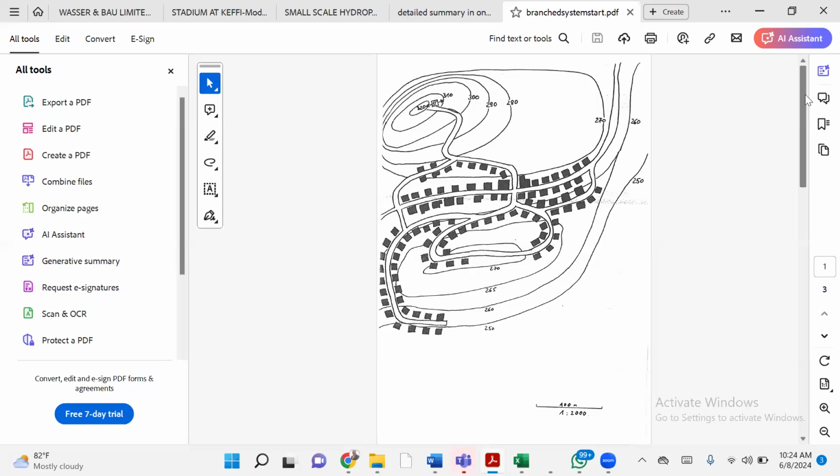So now, you'll be given a map, the topography. As a consultant, you'll be asked to design the water reticulation system, and that is what you have before you. Looking at this map, it's obvious to me that we have an elevation system from 320 to 250. If you supply 320 from 250, that will give you 70 meters. And 70 meters is like 7 bars. We talked about it last week. 70 meters is like 7 bars. It is in your test.